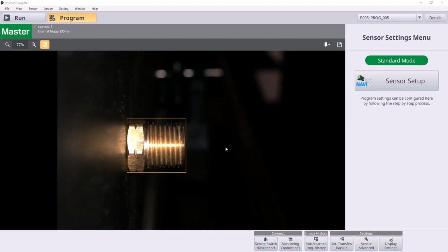Today we're going to be showing you how to connect your IV4 to an Allen Bradley CompactLogix using Studio 5000 and the Logix Designer software. This video will be using a CompactLogix, but it'll work for the vast majority of Allen Bradley systems that support implicit or cyclic communication over Ethernet IP. So as you can see, I've got a little program here already set up.